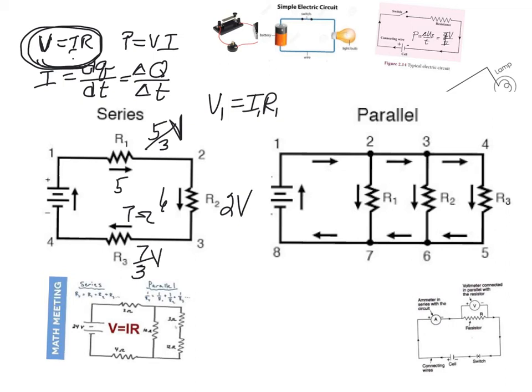So if you take the 5/3 and the 7/3, you get 12/3, which is 4, plus 2 is 6. So you can see that in this case, the voltages add to the total voltage. This is sometimes called a voltage divider. The 6 volts here, there'll be 5/3 of a volt here, 2 volts here, and 7/3 here, and that all adds to the 6 volts.